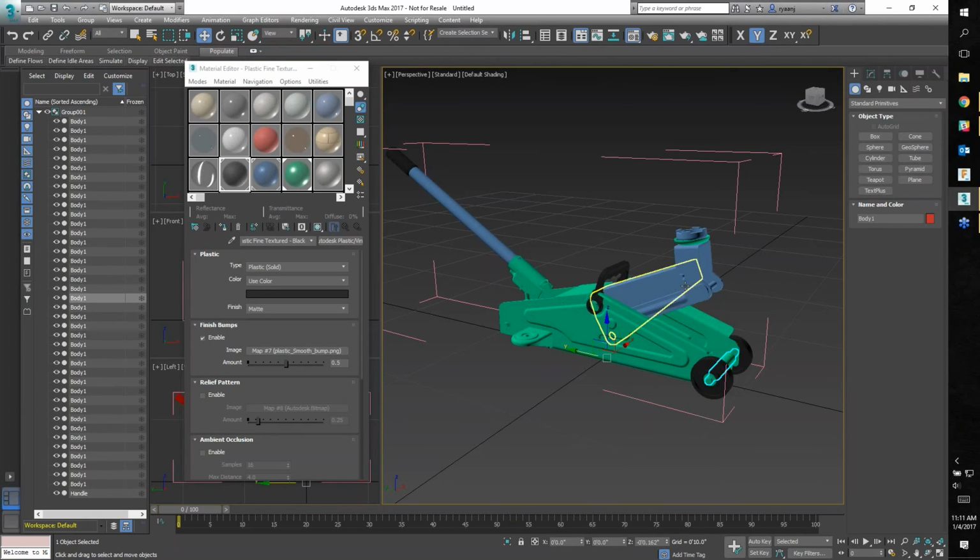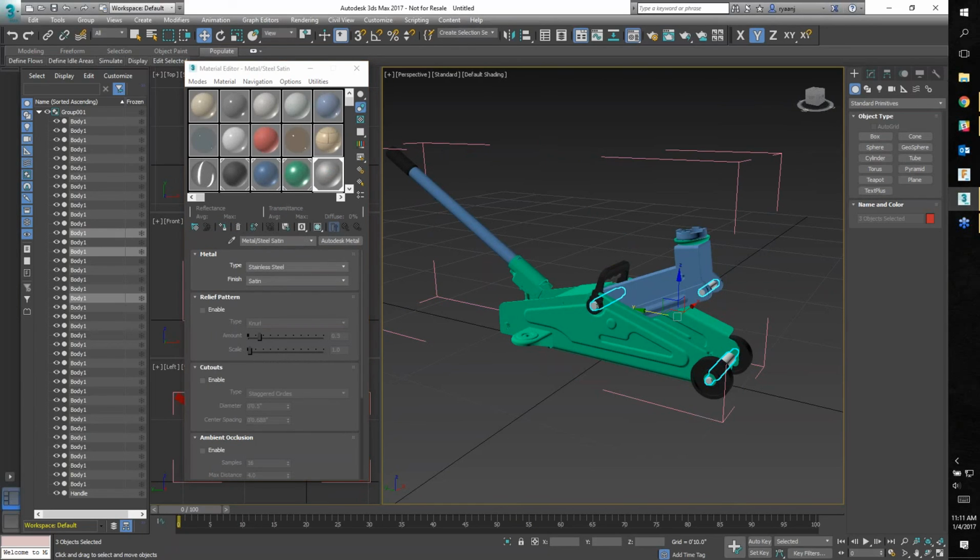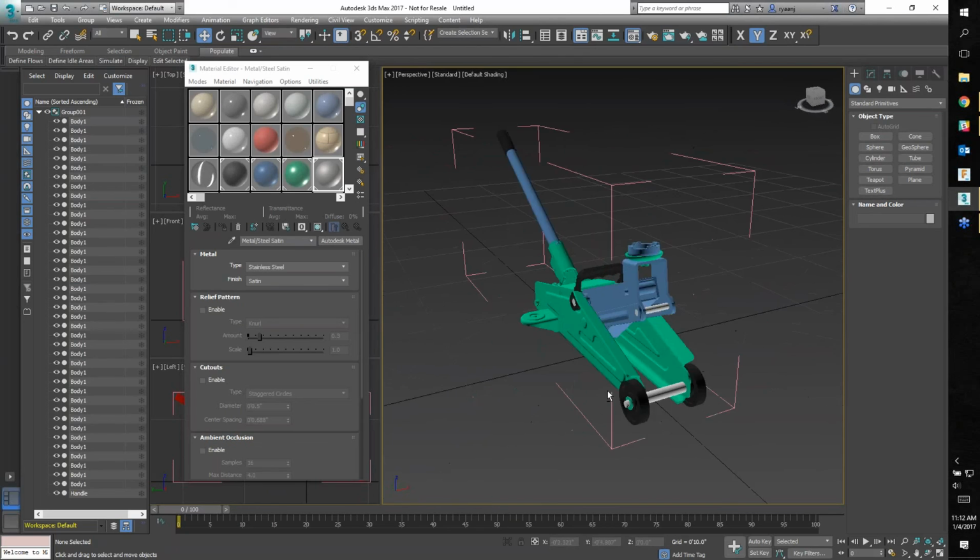We also have a lot of bolts and metal pieces, and these all need to have the metallic appearance. I might mention you can also use the browser to select objects. In this case, they're generically named, so that's not going to be very easy to do. But if I pulled in from Inventor or another file type and they were appropriately named, my guess is in Fusion the file is not named correctly, so they just all called body. But I could very easily pick all the screws from the browser as well and assign materials.